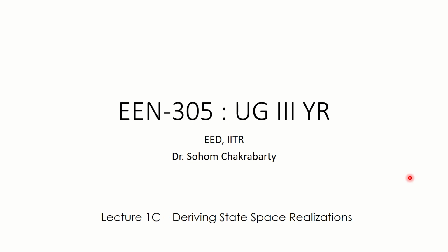If you want to dig deep into that system using state space realizations, you can directly start working from the transfer function. You don't have to go into understanding the actual physical laws governing the system. You have the transfer function, and straight away from there you can derive the state space realization.